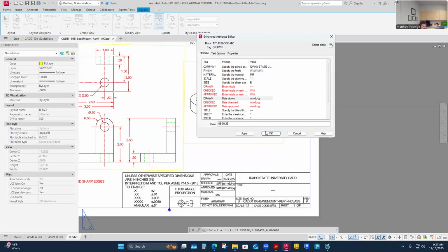One reason why I know there's a revision associated with it is that this date would never change. Once you send it to production, you probably lock it down with that date as when it was. Sometimes it's the approval date when things are approved, might be the timestamp or the stamp they want in the title block. Maybe they want it once the drawing's been completed and sent to the customer or to the in-house fabrication departments, or whatever. There's definitely going to be that controlling date of when it was sent, and that's not going to change ever. Your revisions are going to carry their dates with them as things move forward. Then you get a timestamp on your drawing essentially from everything that's been changed on it.